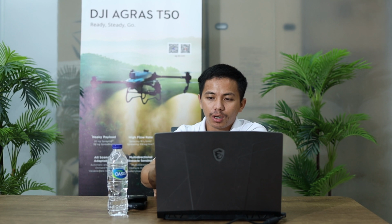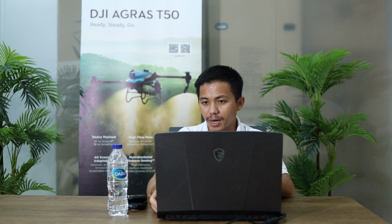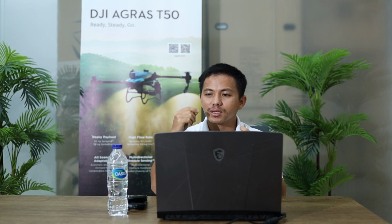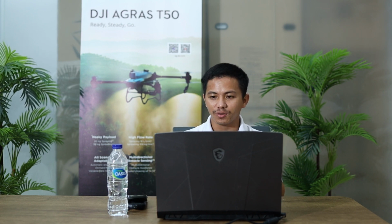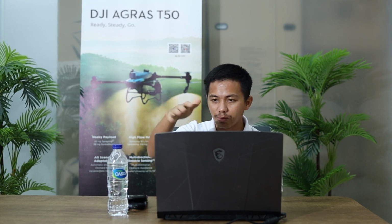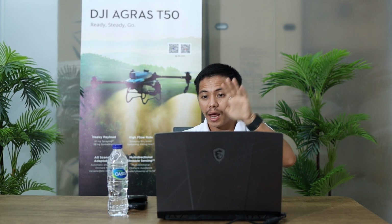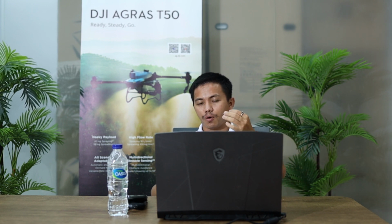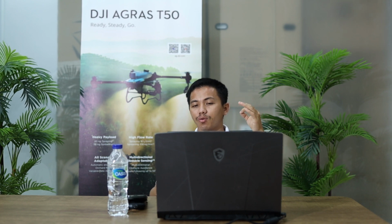So normally our operation is automatic route planning mode, right? But in case of emergency, the pilot must remember his mode. Let's say the drone is mode 1, you are mode 2. In case of some emergency, you want to land. So you may be pressing down, right? For you the throttle is on the left side.